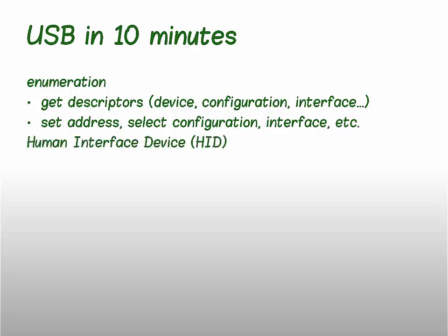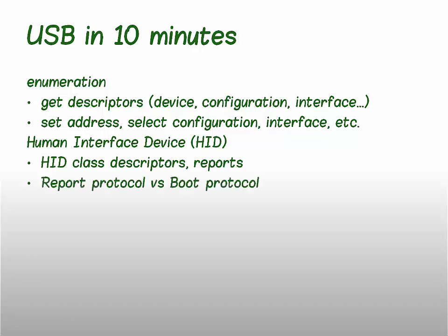There is a distinct type of devices called human interface devices. These devices can provide additional HID class descriptors, which among other things describe reports. This is, in what format the device communicates data to the host. Apart from report protocol, some HIDs support also boot protocol, which is a much simplified version of reporting data. And as you can already guess, keyboards do support boot protocols, and boot protocol is also used in this project.